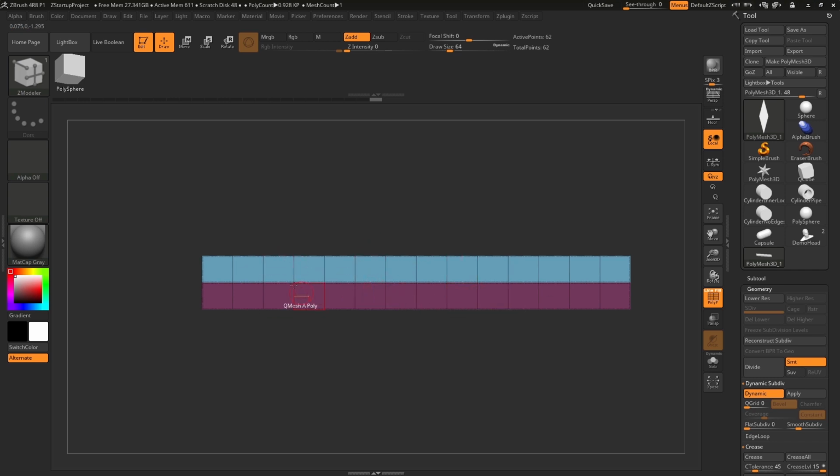Now the next thing I want to do is I want to apply a little bit of a bend. So right now this is very straight. So I want to just take the model and give it a little bit of an arcing up type effect. So as my blade would come down, I want it to arch up a little bit. So to do this bend process, we're going to use a deformer. Now the deformers live inside the Gizmo 3D Customize area. So we will first want to make sure that our model is in edit mode.